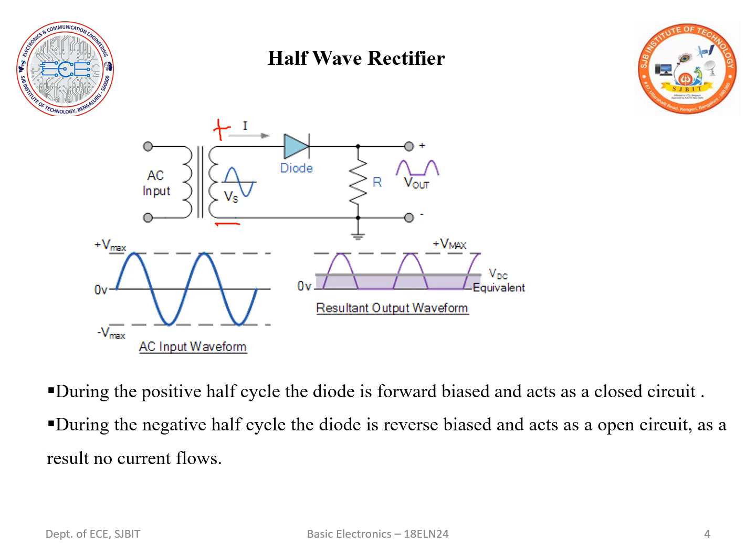During the negative half cycle, the polarities at the secondary winding of the transformer are negative and positive. Looking at these polarities, my diode is now in the reverse bias condition. Once it is reverse biased, the diode acts as an open switch and there will be no flow of current. As a result, there is no conversion of AC into DC, so my output waveform is going to be 0.